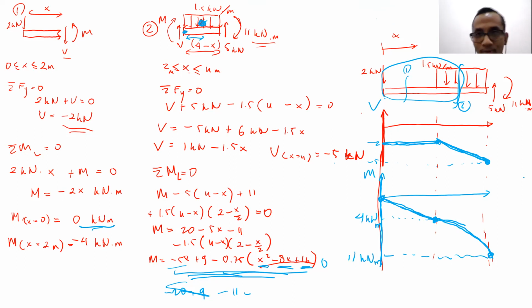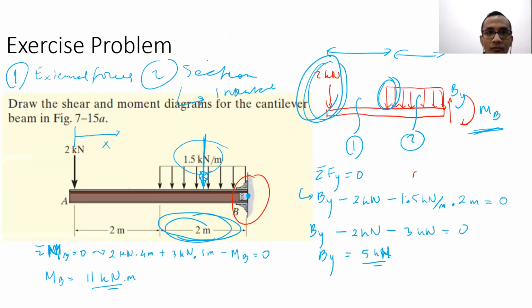Then after I draw the distributed load with the exact length and the exact distance, then after I draw the free body diagram, for example, like this, then I can do the simplification to put the concentrated load to represent the distributed load, but not from the beginning, putting 3 kilonewton there at the distance of 3 meters from the left or 1 meter from the right.